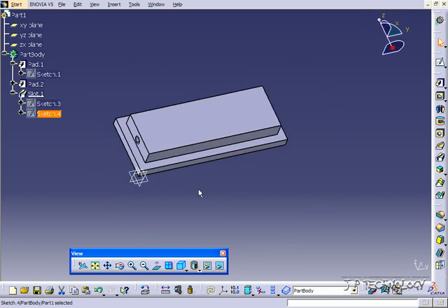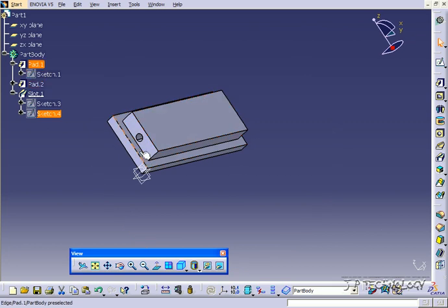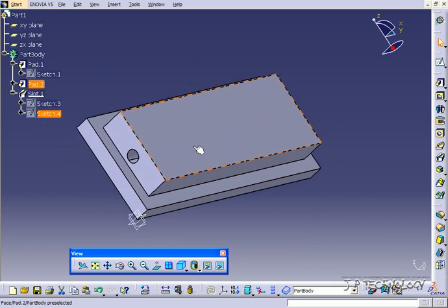So by using the slot feature in an application like this with a hole, you're able to have your dimension of what the hole is going to be, and then draw out and say where it's going to go through, say like a larger block. So kind of like a little pathway and everything for it. So again, this is a tool that's going to save you time, as you're able to create a complex path for it to follow along, and just create one sketch as the profile for it. And this concludes our tutorial on how to use the slot feature within CATIA v5.